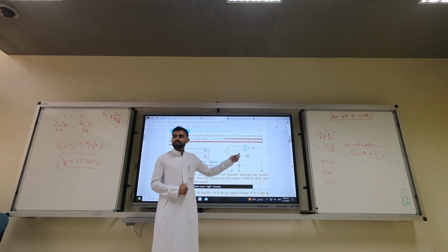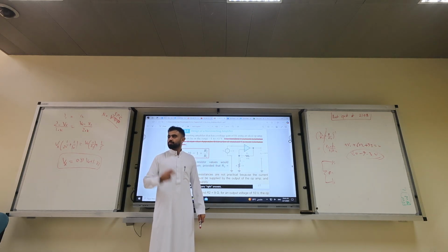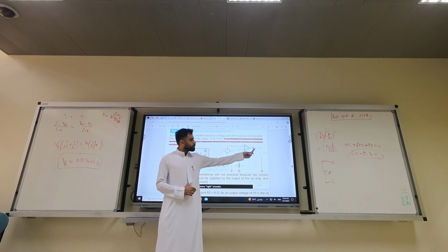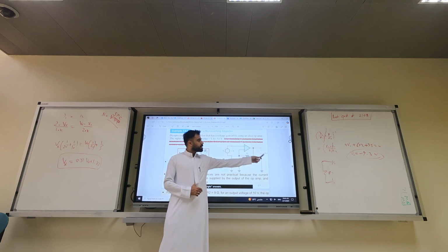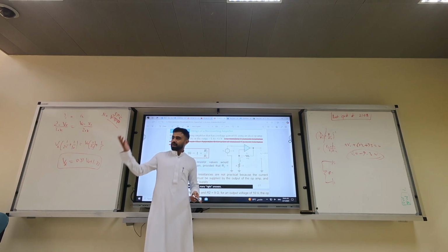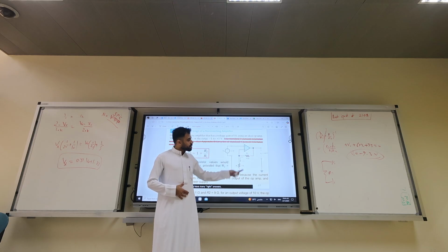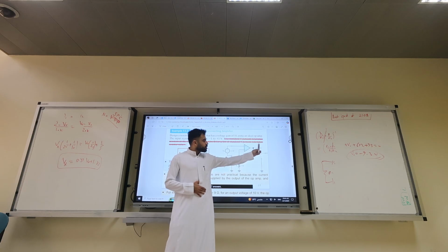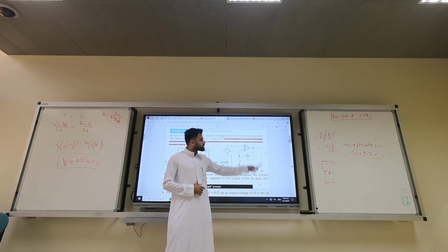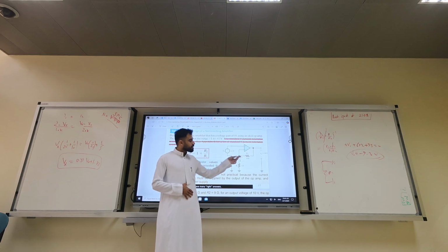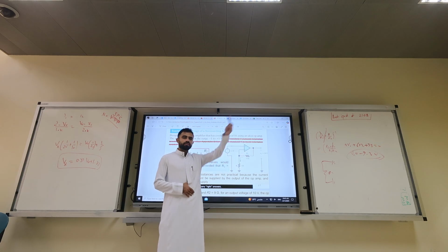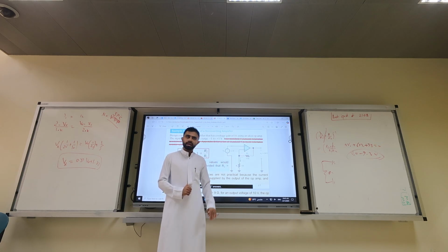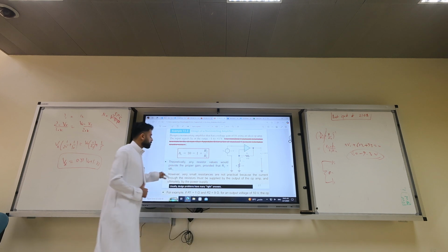Why do we not like small resistors, meaning 1 ohm, 2 ohm, 3 ohm, 10 ohm, which make the current higher? Because if you have an output of, let's say, 10 volt, 10 over a small resistor is a big current. So this current will go here while you need it to drive the output. So if you connect a speaker here, it will draw the current from the supply, and you are wasting current in the feedback. Why waste the current in the feedback, where you can achieve it with big values of resistance? But again, there is also a limit for